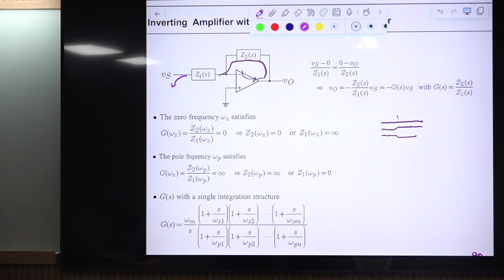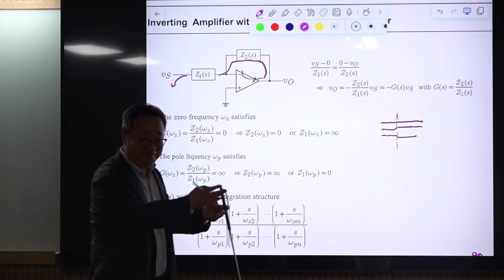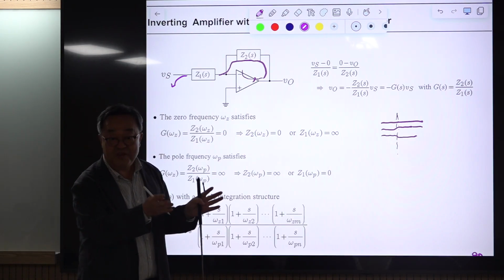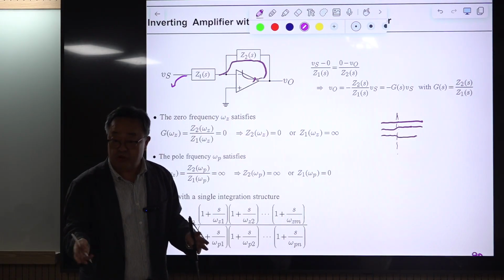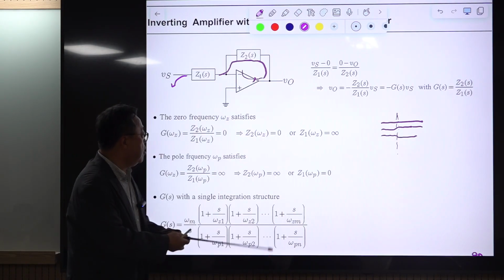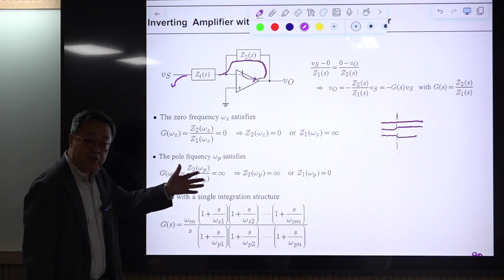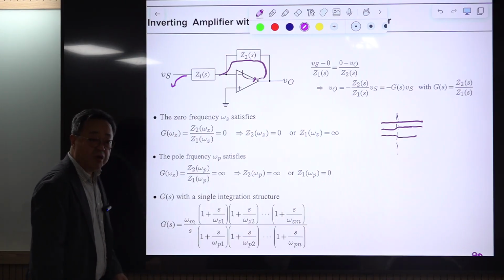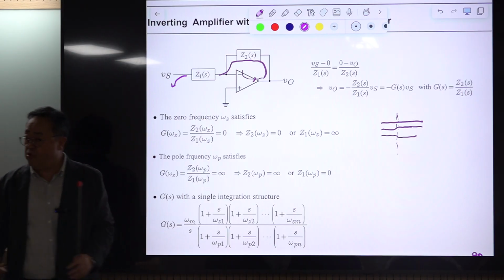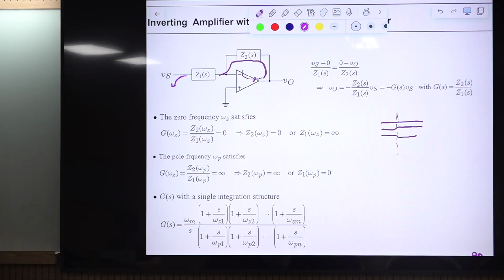This is the location of the cancellation. Okay, you need some imagination here, I'm using some analogy. But if you try to cancel a double pole with a double zero, that will be impossible, because a slight mismatch will produce what? I said that. This one or this one.